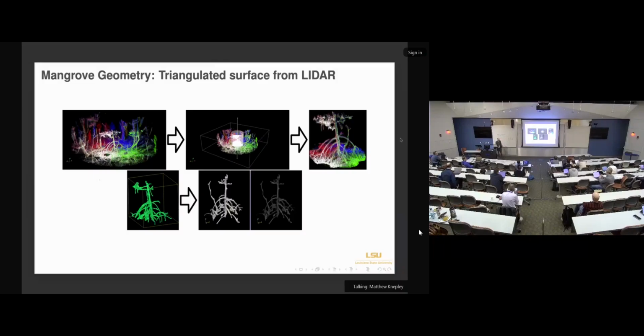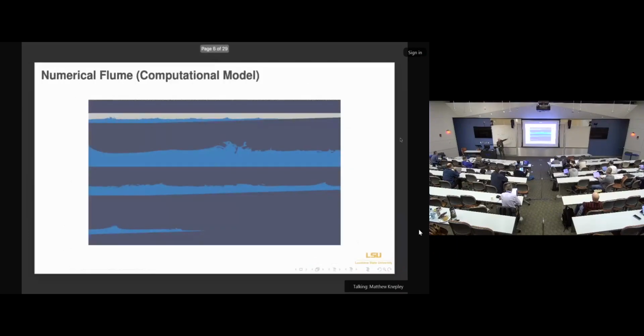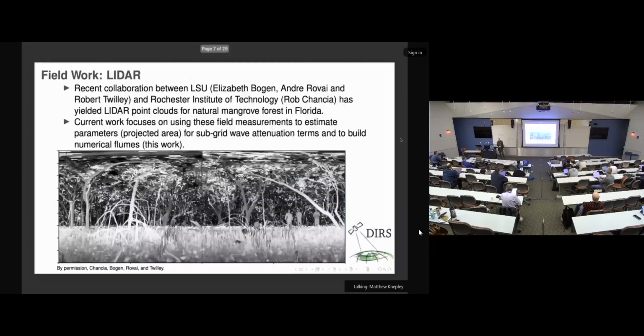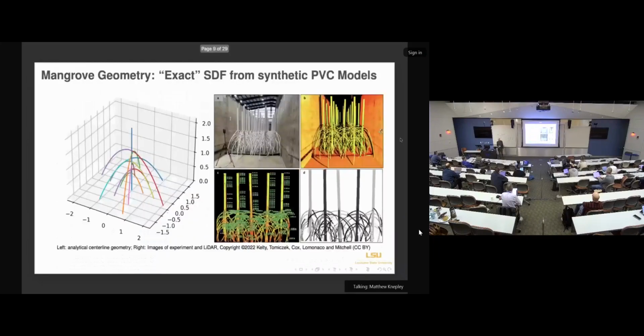We're typically not successful at generating boundary-conforming meshes with standard mesh generation software. So because we had been looking at level set methods for the complex free surfaces that we have to model, we thought, well, let's start using embedded solids using level set descriptions of these vegetation structures. So that's part of the method that I'll talk about today.